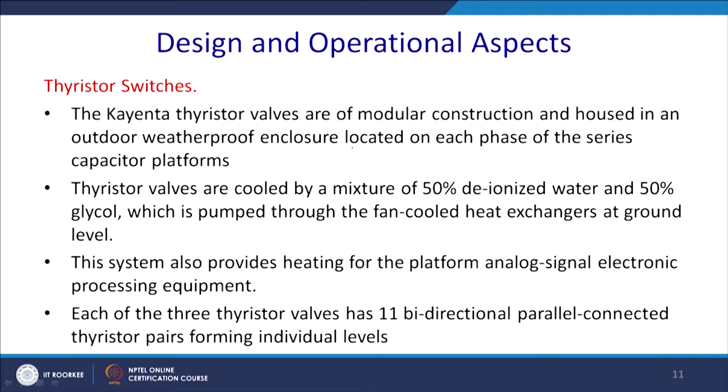Thyristor valves are cooled by a mixture of deionized water and 50% glycol, which is pumped through a fan cooled, that means force air cooled, heat exchanger at ground level. The system also provides heating for the platform of the analog signal electronic processing equipment, so it will also maintain the ambient temperature for those components.